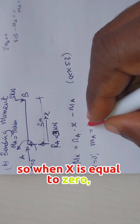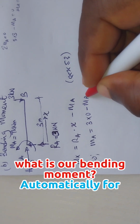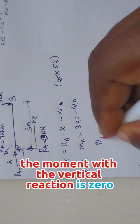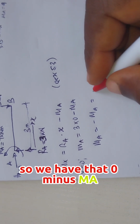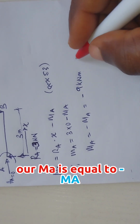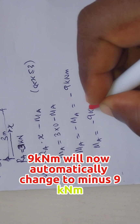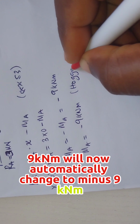So when x is equal to 0, what is our bending moment? Automatically, the vertical reaction at point A contributes a moment of 0. So we have 0 minus MA. So at the support, our moment is equal to minus MA. That MA we got as 9 kilonewton meter will now automatically change to minus 9 kilonewton meter.